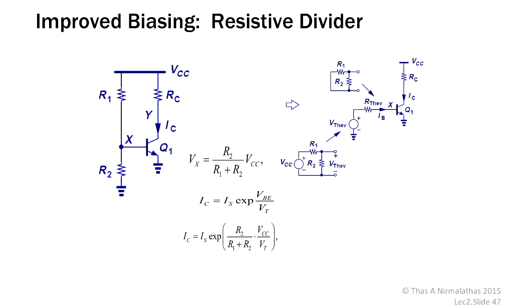There will be some variation in the circuit, but not like beta, because beta variation is more prominent, because beta is the current gain. If that is varying from 100 to 120, then there is a big variation. So this one is relatively better, though there is some temperature dependence. It is better because it's not depending upon the beta. Another thing is that the temperature dependence of resistance is not affecting much here because of the ratio. So this is relatively better. And then IC is relatively independent of beta if base current is small. I said base current is small.